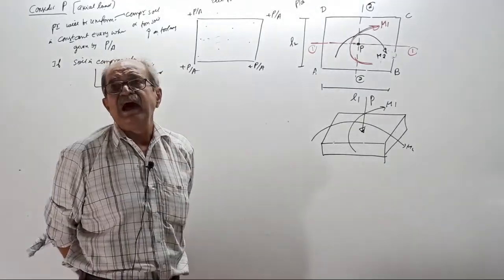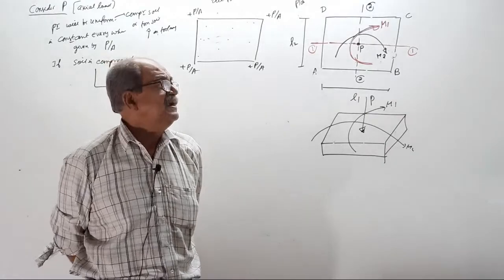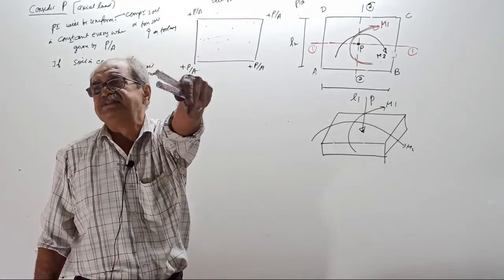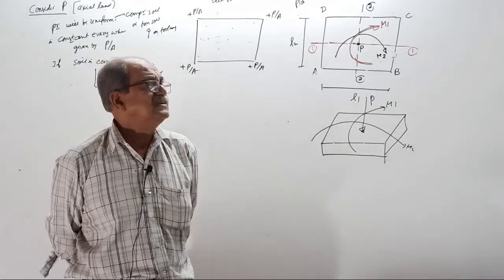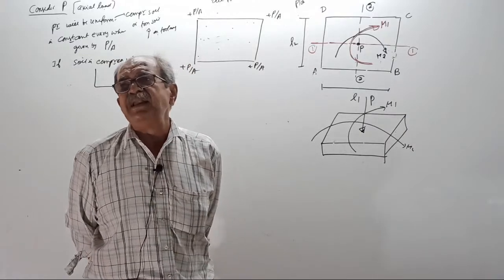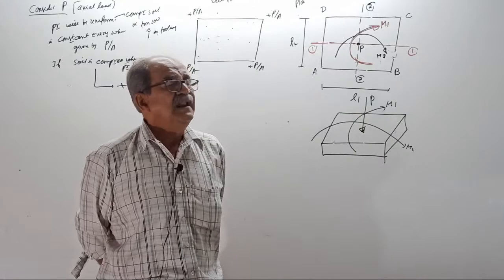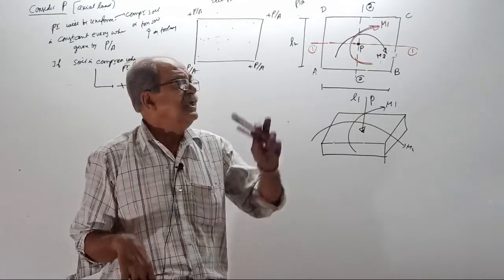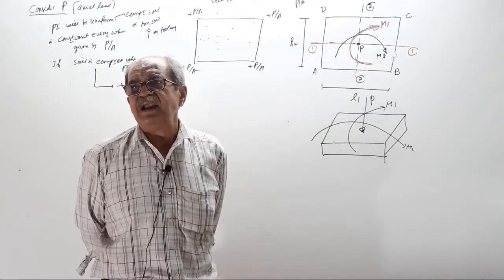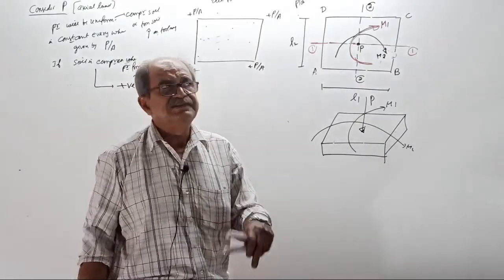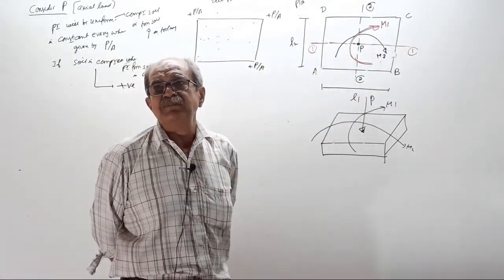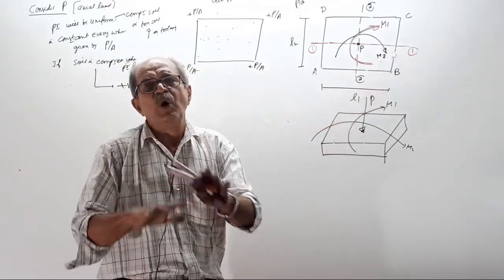But remember, technically this is wrong. Because of soil settlement, soil subgrade reaction, pressure will vary. We are not considering that, but software will consider it, because there you give the soil subgrade reaction. We don't consider it. We are going as per strength of materials, meaning unyielding soil. If uniform settlement is there, no problem. If non-uniform settlement is there, there will be slight variation that in class we are ignoring. When you assign subgrade reaction to the footing slab in software, I will tell you later, in the ETABS class. Then the result from our class and the result from software will vary slightly. Here pressure can come 120, there it may come 118 to 125. Okay, leave it.